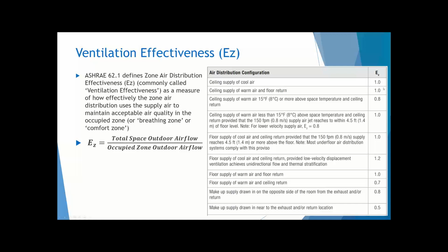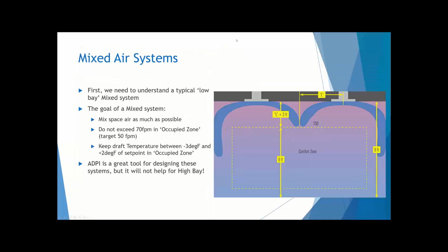So let's look again at mixed systems. Before we get into high bay mixed systems, let's first understand exactly what we'll consider, at least for the sake of this presentation, a low bay system to be. I mentioned earlier that ADPI does a great job of helping us understand how to define or design around a low bay system. But basically the goal of a low bay system, or really any mixed system, is that you're trying to mix that airspace as much as possible.